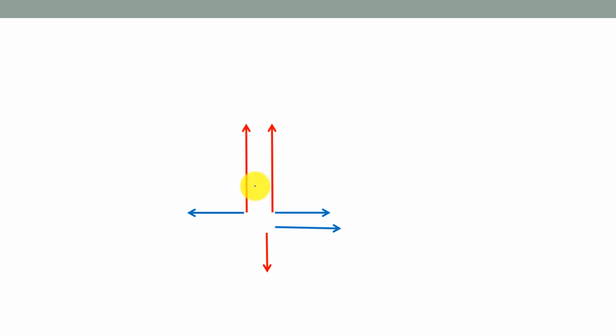So we now want to add them. First of all, we are going to add the forces which are in the same direction. Now, we realize that this one plus this one will be 8.66 plus another 8.66, because the idea is to try and arrange the forces head to tail, those which are acting in the same direction, like this.